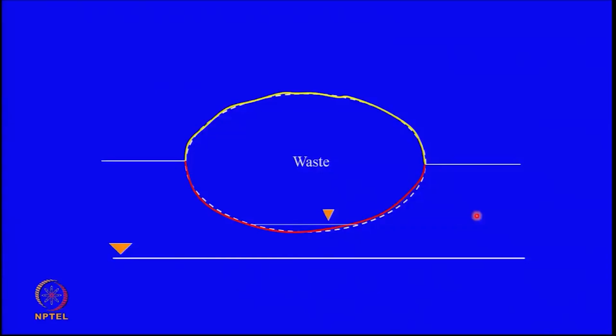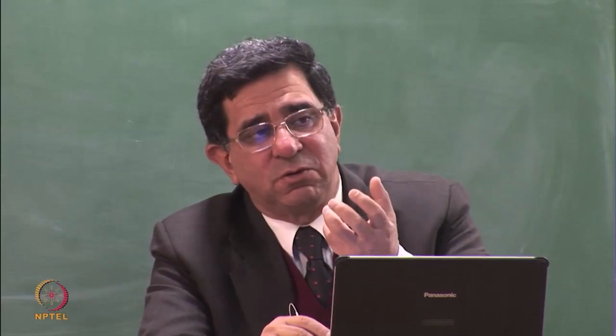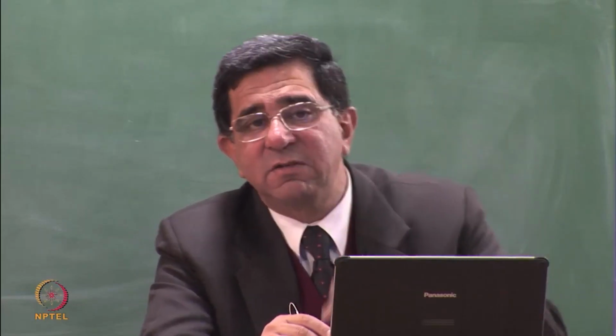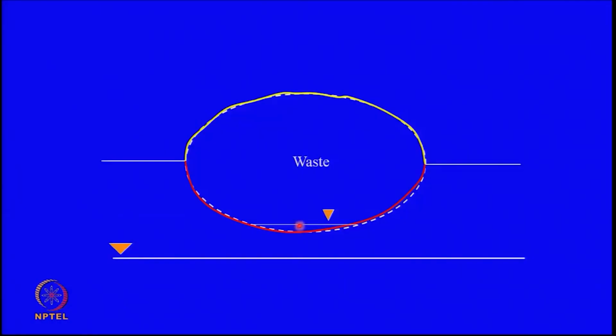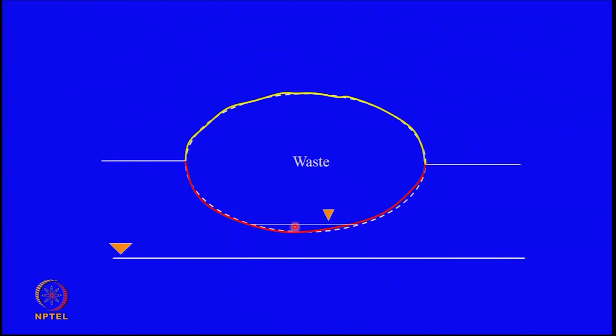Even if there is no rain, the waste is wet. It's food waste. It has liquids in it. So after some time, the liquid will squeeze out from the pores, because you have got normal stress acting on the waste, and this leachate will collect here. A little amount, pretty concentrated. Typically you can just see it as concentrated saline solution, because at least the salt will come out in it. And if it is this problem, we should not be bothered, because we have an impermeable liner at the bottom.